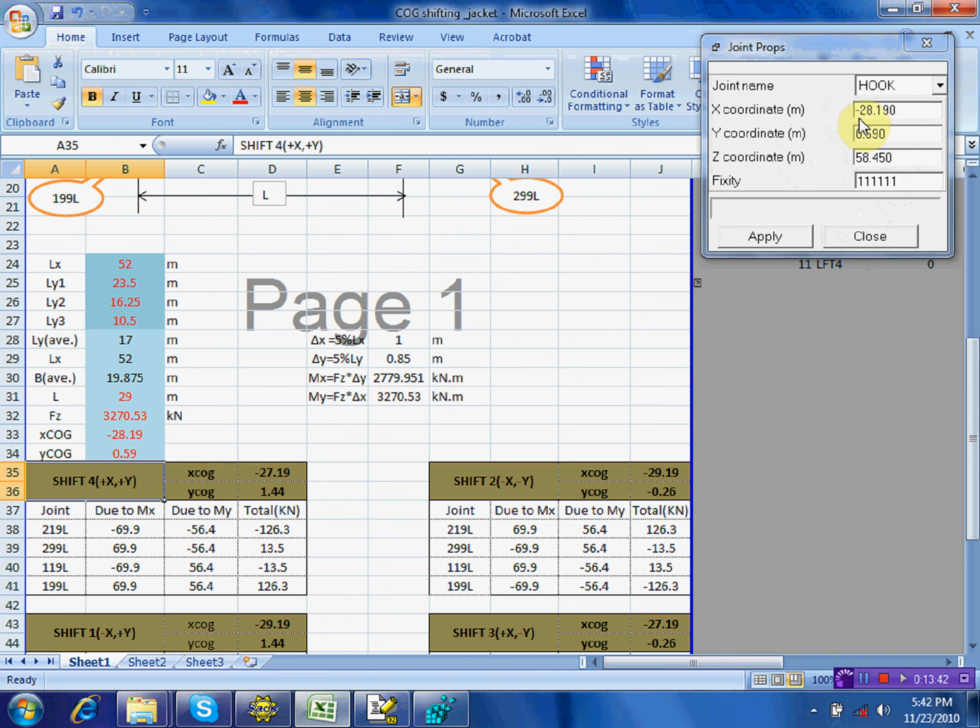Okay, you update. So your Z, copy, you have already copied that one across? Okay. If Z is gravity load. This one, yeah. So you have to update that one. Update the value of X because we add pad eye load, we add cone guide load, so your X and Y will change. You have to update that.